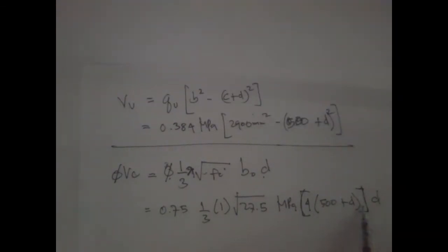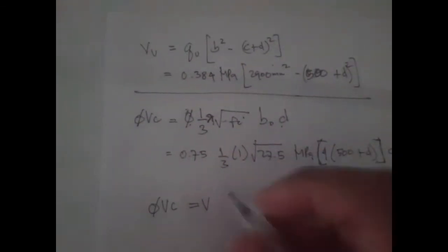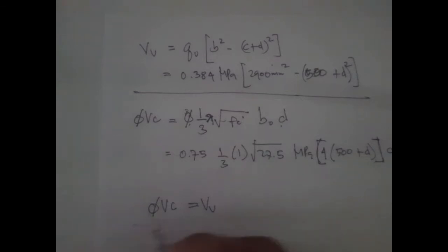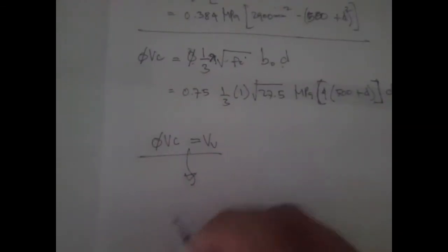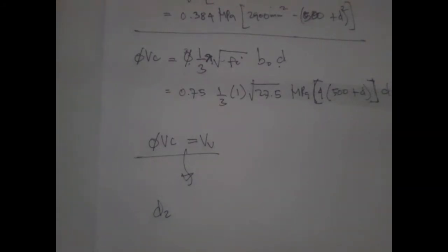Now since you have the 2 equations, if you equate Vc to the factored loads, you'll be able to compute for d.